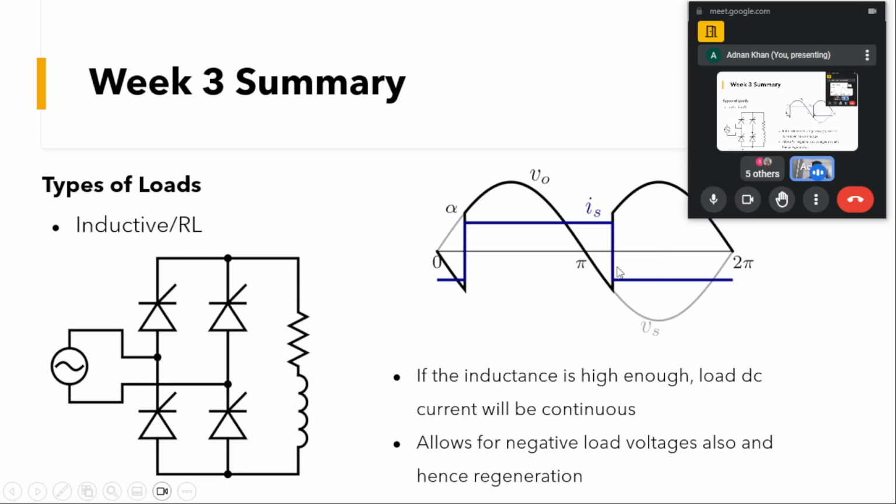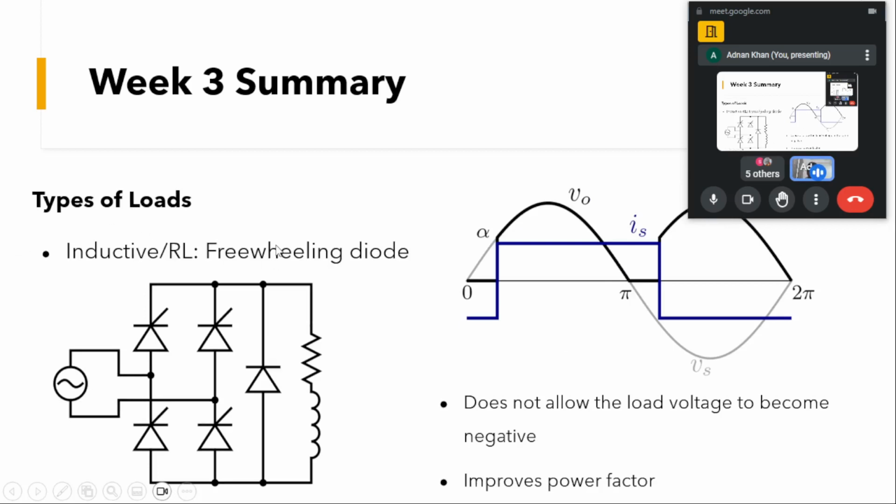Now here we had seen that because of this inductance, we had this negative part of the voltage, and somewhat our average voltage magnitude at the output was decreased. So now we will look into whether we can still have only the positive voltages at the output, and can we somehow clip this, or not have this negative part at the output.